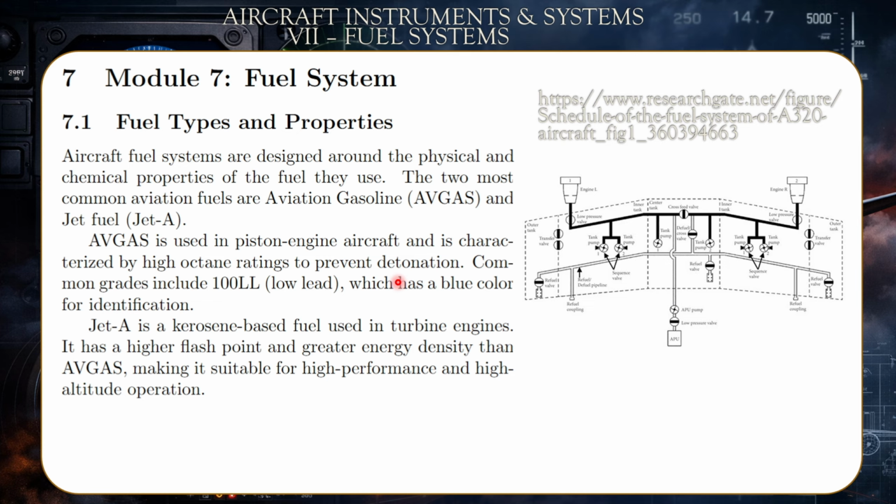This is why a six-wheeler usually runs on diesel, because it requires higher torque. It is a heavy transport vehicle, as you know. It requires a higher torque and a slow combustion rate. Meanwhile, your average car requires the alternative. Why? Because it needs to combust quickly, and it has lower torque requirements but more speed requirements. It needs the fuel to ignite much faster in order to turn the engine at a higher rate.